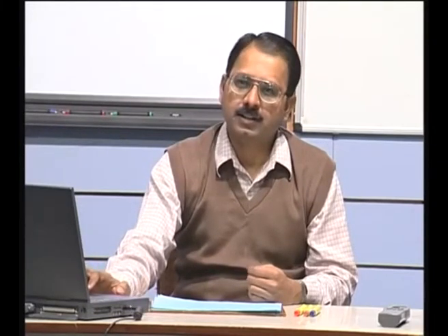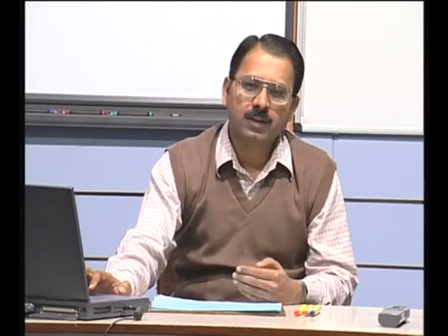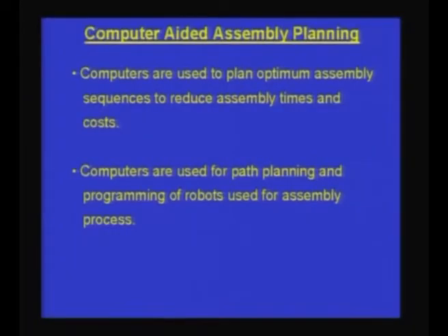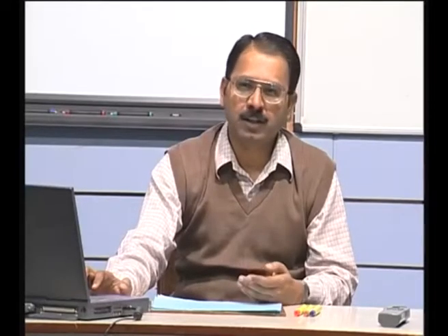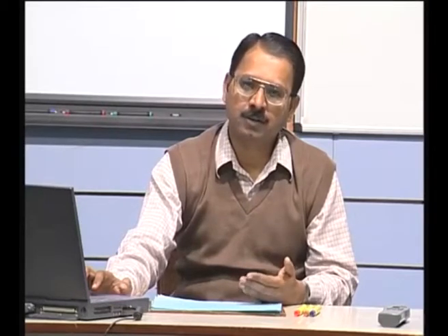Last time we also looked at, as a part of our computer aided design lecture, that assembly is one of the important aspects in product design and manufacturing. Now, assembly execution is usually a part of a manufacturing process. If there are a number of components which have to be put together as part of an assembly, there can be a number of assembly sequences which are possible. These assembly sequences can be generated as a part of computer aided assembly planning, so that the time involved in assembly can be reduced, or the cost involved can be reduced, or I am looking at both,